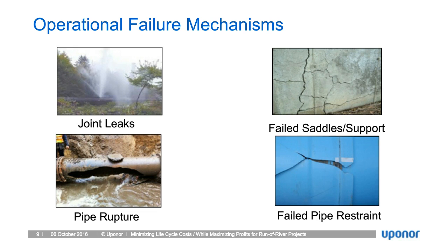Pipe ruptures could be because of tensile strengths. When you have support saddles, if the saddles fail, it puts tensile stress or pressure on the pipe. It could also be just metal fatigue. Transient or pulsating pressures could fatigue the metal. These are different reasons why pipe ruptures could occur.